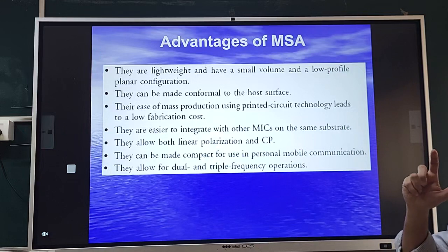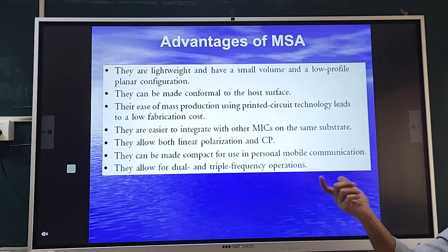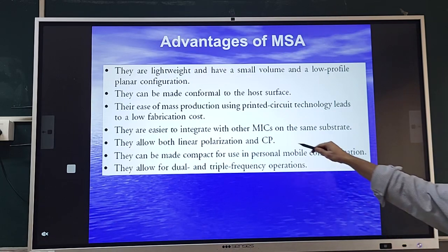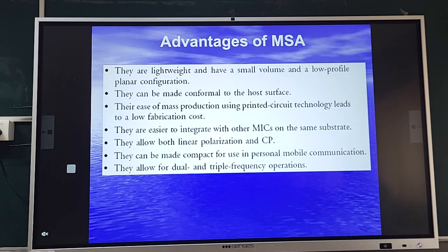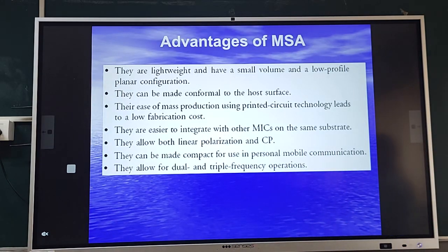So doing mass production in bulk is very easy; I should say, we use it for microstrip antenna design. Okay, now this is a very important design aspect. For realizing circular polarization or dual polarization, you require multiple antennas if I use a dipole. For example, those who have gone to GMRT must have seen two orthogonal dipoles used to pick up two signals.